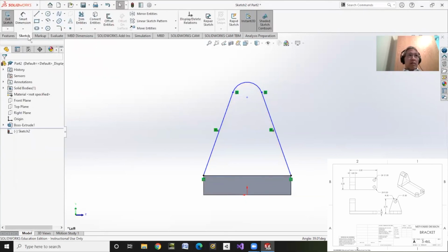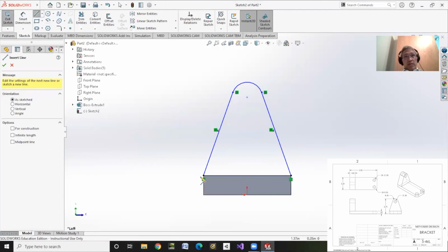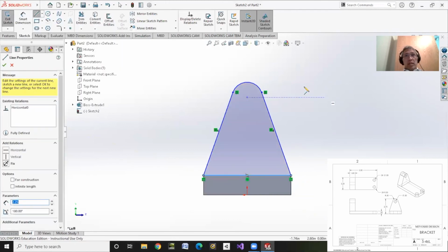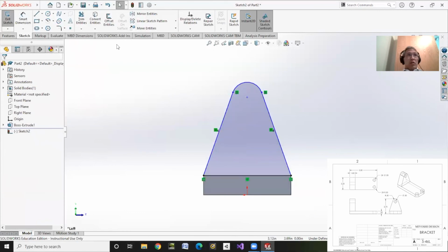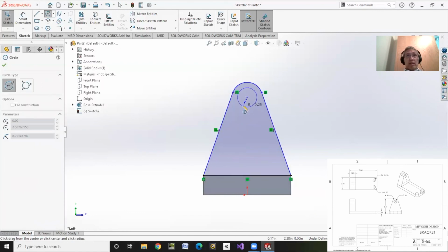So what we have to do is make one more line. So I'll go back to sketch. I'm still in the sketch. Now I just make a line from this endpoint to this endpoint, and now it's a closed figure. I'll do select. I'm going to do two more things. I'm going to make a circle because I don't want to make the hole later. I'll just make the circle. Again, it's concentric with the other one, so I'll just grab that center.